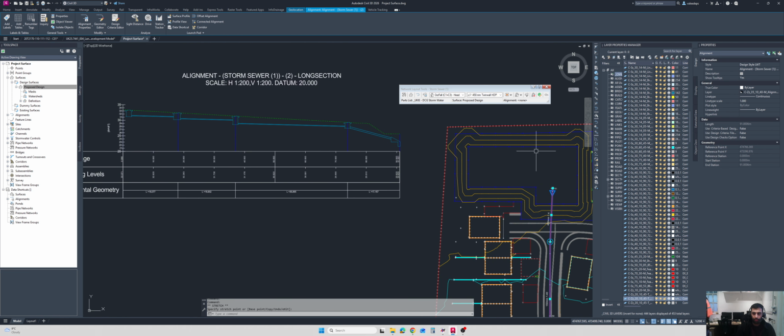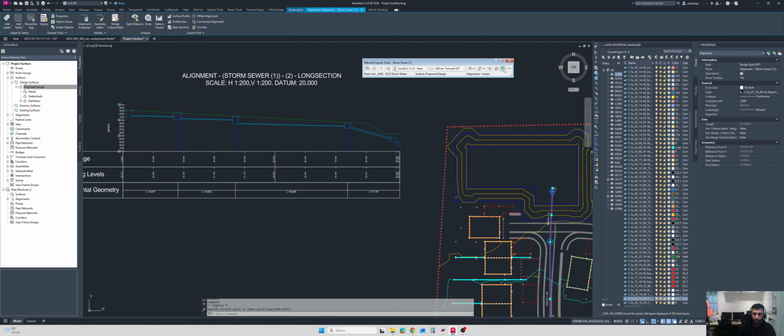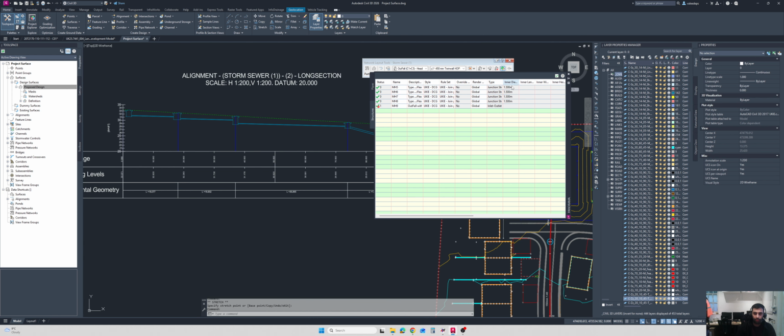In the network layout tools, you also have this icon, pipe network. If you click here, you will see errors like rule applies to junction structures only. These are the ways you can see what is proper and what's not, and what you want to edit or what you cannot edit.